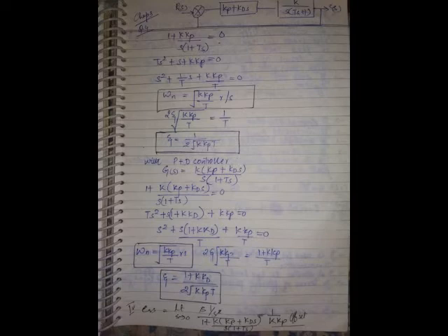So if you observe, for sinusoidal input, is the phase of the controller output leading or lagging? By how much angle is it leading? Tan inverse omega Td. Now the difference between only D and PD is, in only D, the phase lead is 90 degrees. You can't change it, which means the anticipatory nature of a derivative controller you cannot control there.